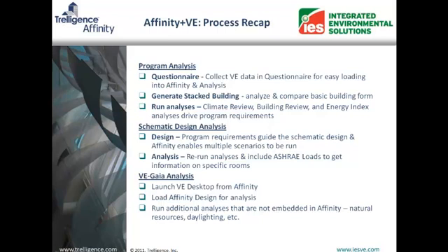And in the Affinity schematic design, we can run multiple scenarios of the building for comparison purposes to find the most optimal building form and adjust any project properties prior to moving into the detailed design. We can also rerun previous analyses like the ASHRAE loads, which gives us information on specific rooms. And finally, we can launch VE Gaia directly from within Affinity for more detailed analysis like daylighting.